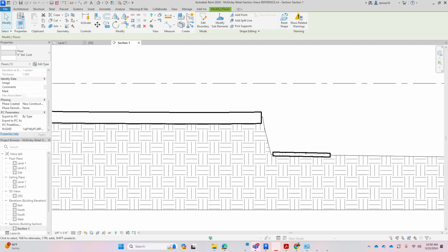Well, for a retaining rock wall, you'd have to look at the construction details that were drawn already, but you would have a footing right in here, which is usually about 1 foot deep. And then you have the height of the rock wall, and this is a surface where it's considered retaining. It's retaining the difference in elevation from one to the other. The height from here up this way, we don't know that. As a matter of fact, it doesn't show up on our detail. So for now, just go ahead and draw it 1 foot higher from this elevation.